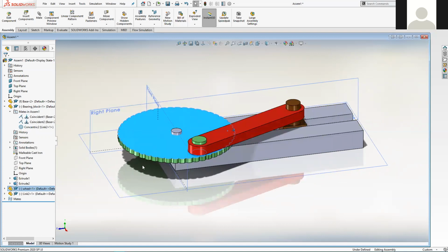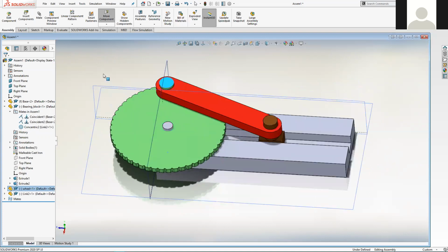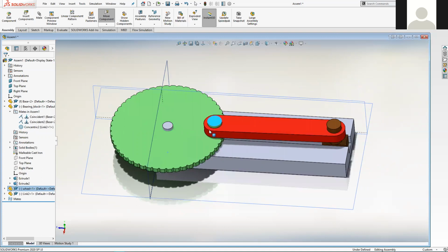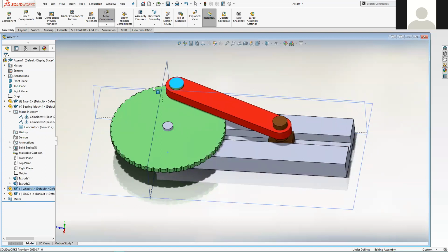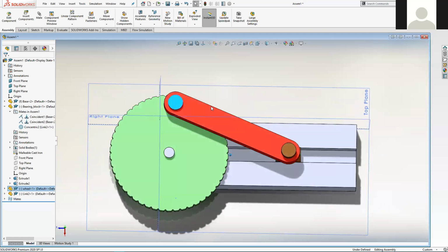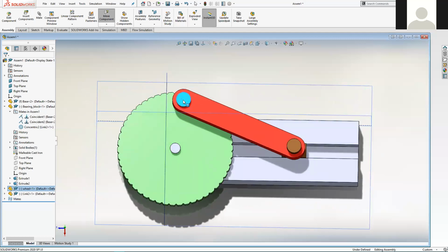So that's sort of the easy bit. Setting up the assembly is just a bit more practice for us building assemblies. It's not really part of the simulation step. So there is a step here before we drop into motion simulation that you're going to want to do. It's wise to set the bearing block there to about halfway through its travel. It seems to present fewer problems.